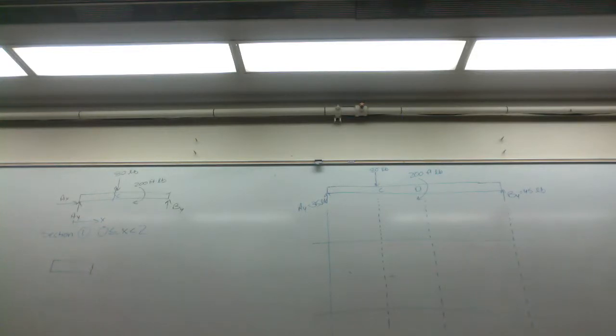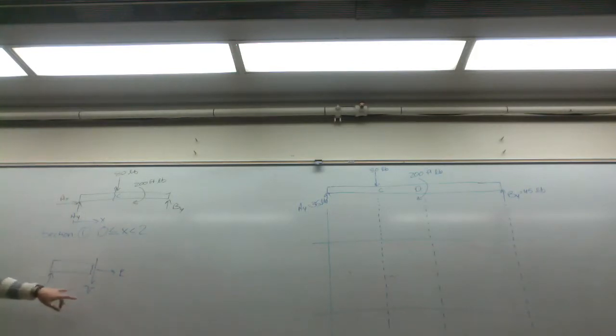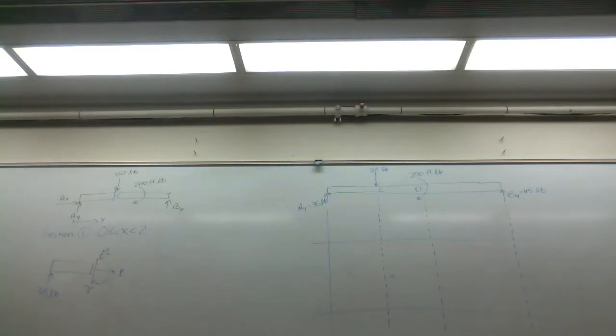the same way you learned on Monday, the same way you just did your homework on, you apply your external forces, your external reactions in this case, at A, and now we draw our internal forces at this cut with the positive sign convention. So we know our shear is pointing down, it's trying to push the right-hand side down. Our bending moment is in a counterclockwise position, it's trying to go concave up, and our axial force is in tension. And we know that's going to be 0.